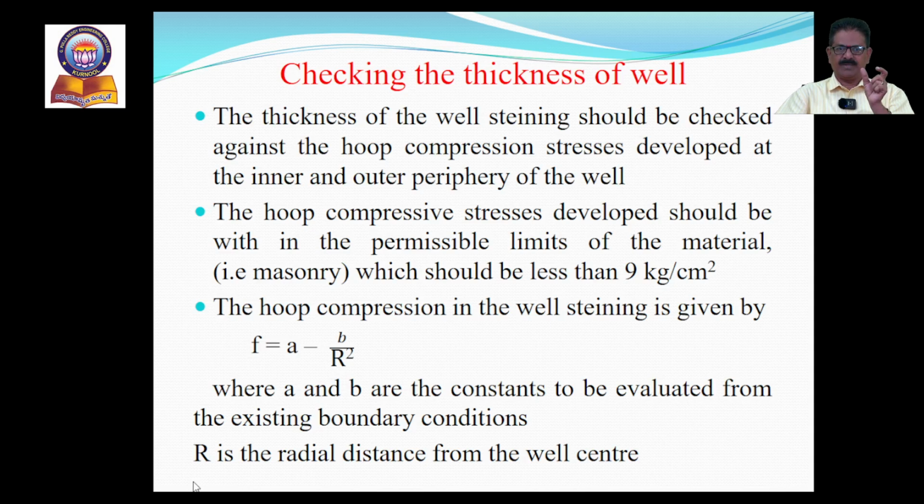Whatever the thickness may be, inside the well and outside the well, within the well steining, hoop stresses will develop as it is in circular shape. So we are going to check whether these hoop stresses developed within the well steining, both inside and outside, are within the limit or not. That is our task.